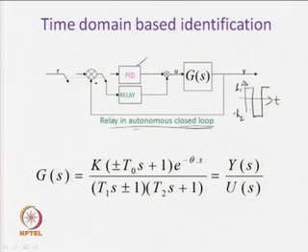To obtain sustained oscillatory output with different peak amplitudes and different half periods. That will enable us to measure more than two parameters from the sustained oscillatory output. When we measure more than two parameters, the analysis will enable us to estimate more than two unknowns associated with a transfer function model for the dynamics of a real time system.